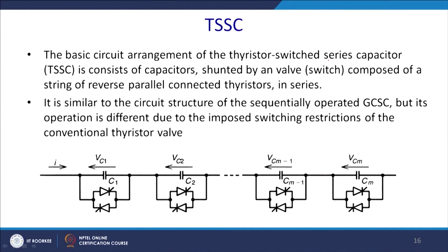The basic circuit arrangement of the thyristor switched capacitor: see the logic here. You will have a series capacitor and an anti-parallel thyristor connected with it. It is just the opposite of the TCR. The thyristors have to be put in parallel with the capacitor.